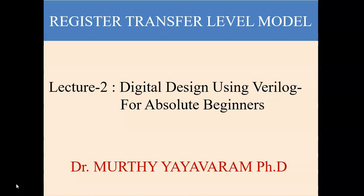In the declaration part, we declare the name of the module and the I/O ports, input and output ports, and in the body, we explain the relation between outputs and inputs. Every module ends with the statement endmodule. For this, we took one or two examples in the earlier video.